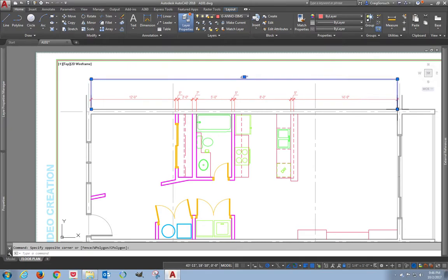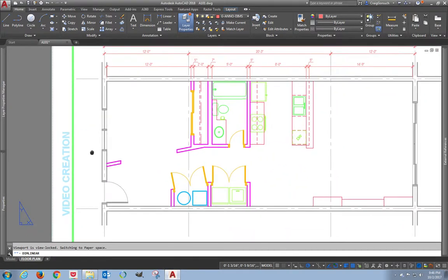When we originally drew our floor plan out, remember we had dimensions that were running to the center lines, or the grid lines. So let's put that dimension on the grid lines. Let's put another string of dimensions here, showing the existing grid lines, and let's put them vertically as well, right there.